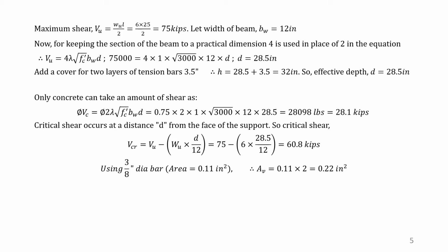Here, first of all, we have to choose the beam width. Sometimes we get all these dimensions of the beam from moment consideration, and in that case we don't have to assume values. But here, as we are not relating this problem with moment, we have to find the beam width first. Otherwise we cannot solve this problem.